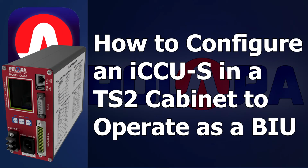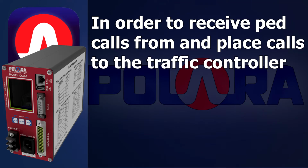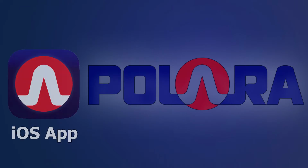This video will demonstrate how to configure an iCCU-S in a TS2 cabinet to operate as a BIU in order to receive PED calls from and place calls to the traffic controller. This configuration eliminates the need to install the 50-pin connector and connect the associated wires. For this video, we will use the Polara iOS app, but the process is similar with iNavigator apps for other platforms.